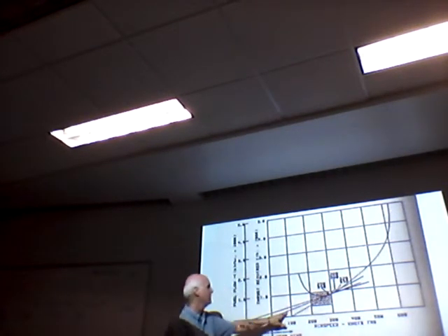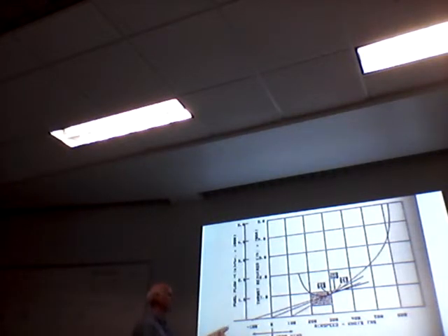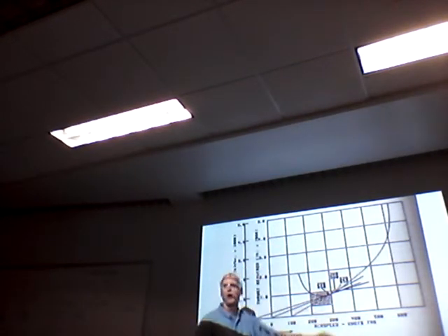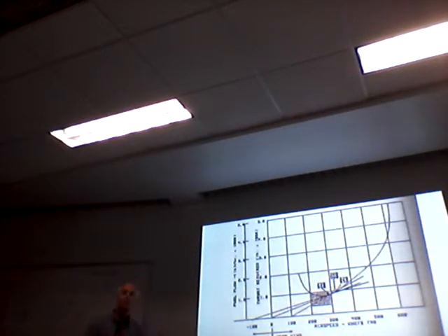This would be zero wind. That's my airspeed. How about for a tailwind? It would be somewhere this side of the origin. But if I didn't have this chart that has headwind, tailwind on it, and I said, hey, you've got a headwind you're flying into, could you not just start at the 100 knot point and come up with a different tangent and determine what your most efficient speed is to do the climb?